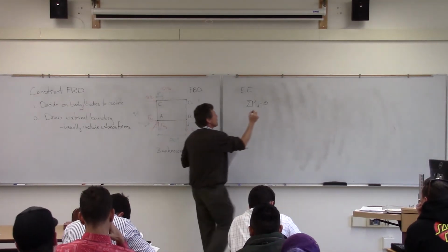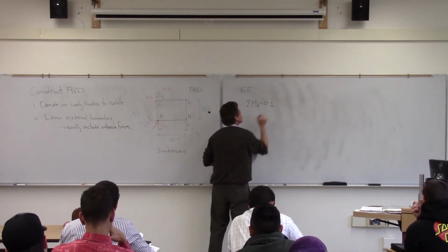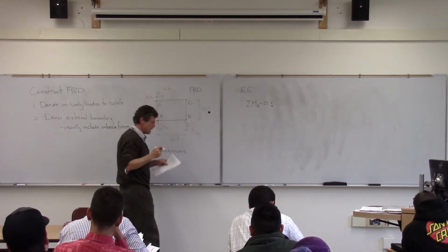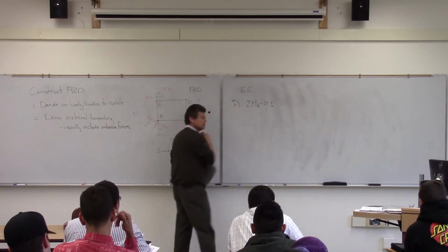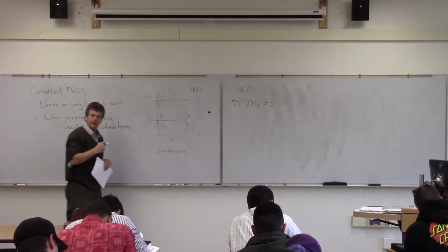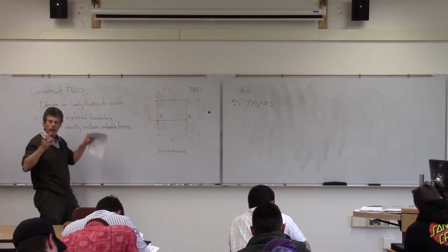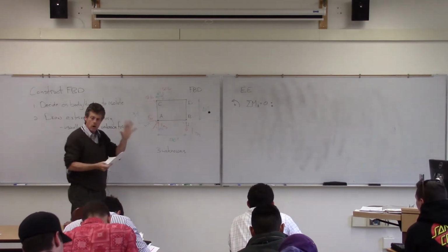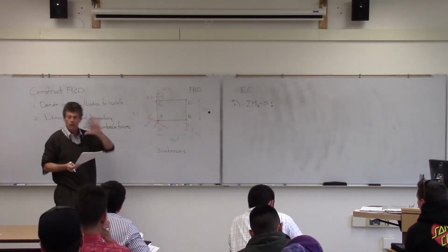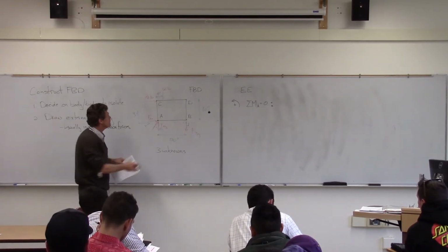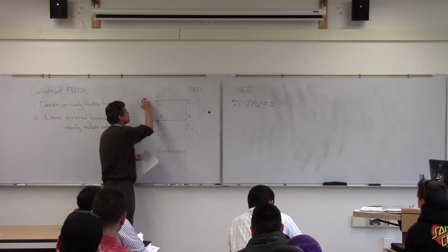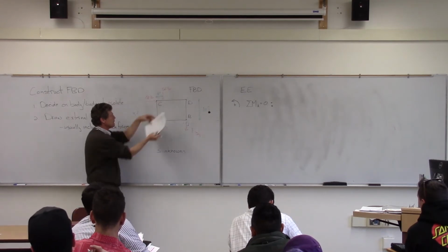Now, when I set up my equilibrium equation, I'll set moment at A equal to 0, and then I'll choose my positive convention. And again, I'm choosing it for this equation. And moments are twists. So whether the force is negative or positive doesn't matter. It's how it's twisting the body. So the 40, when we think about A there, we've got this 40.